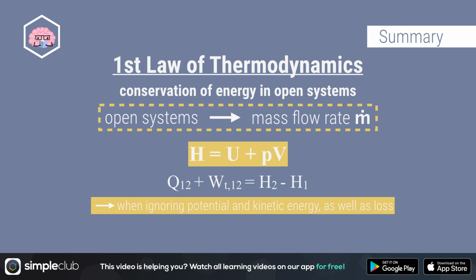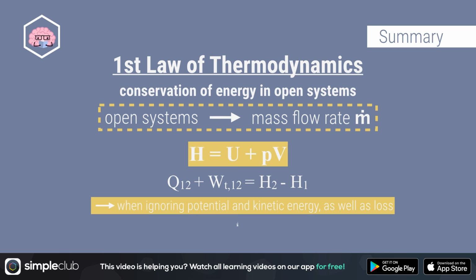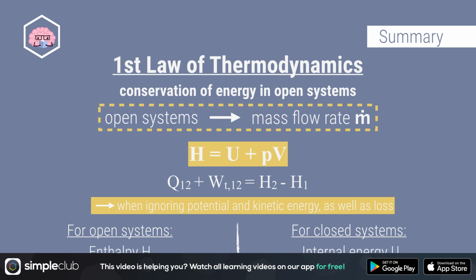Don't forget that we left out kinetic and potential energy here, along with loss. If you put in all that stuff, the equation would look like this. We'll look at this form of the equation another time. As a rule of thumb, you can basically say that enthalpy H is always relevant in an open system. And with closed systems, the important thing is internal energy U.